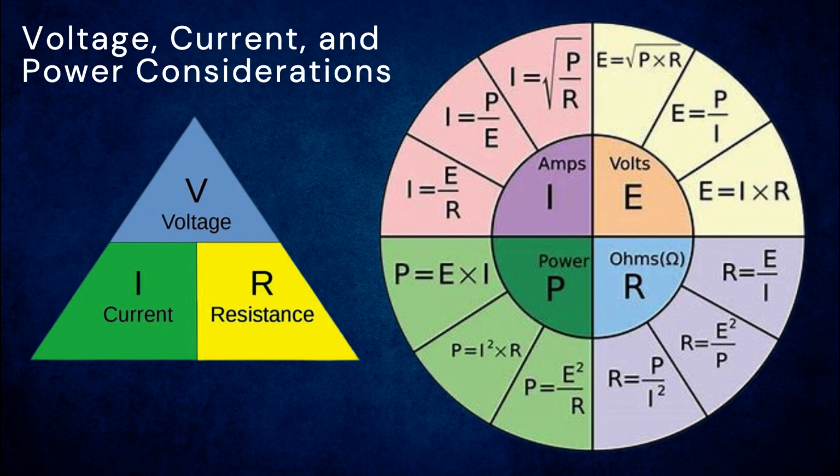Power factor, efficiency and real power. In addition to apparent power, the product of voltage and current, power factor is a consideration in electrical calculations. It reflects the efficiency of power utilization in alternating current, AC, circuits. Power factor accounts for the phase difference between voltage and current waveforms and indicates how effectively power is being used. Correcting power factor is important in industrial settings to avoid penalties from utility companies and optimize the efficiency of power distribution systems.